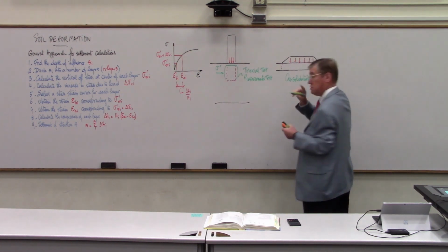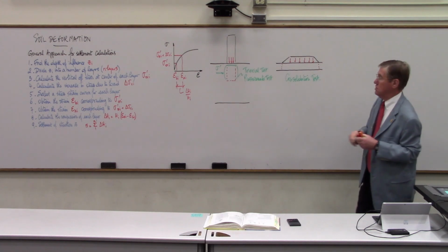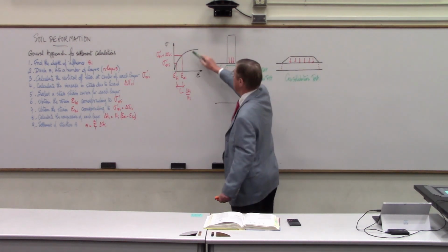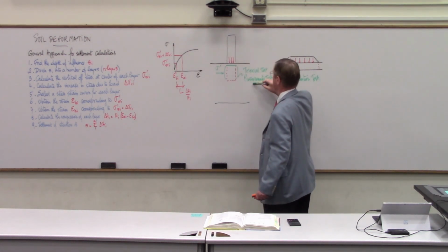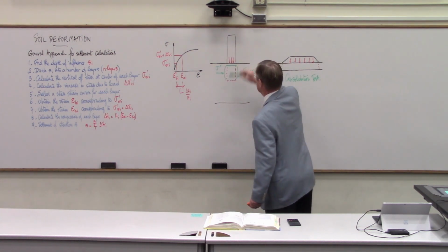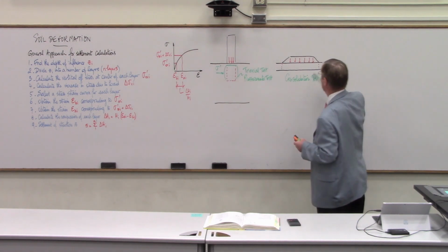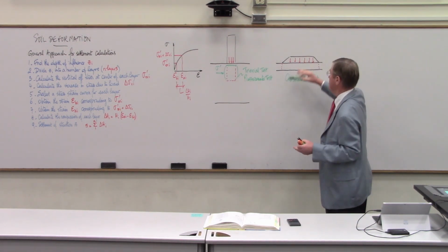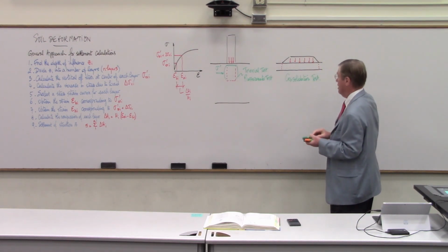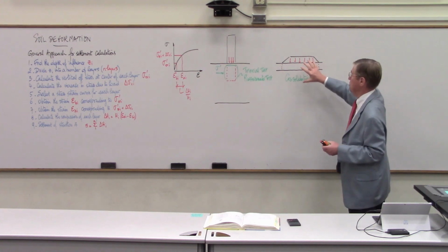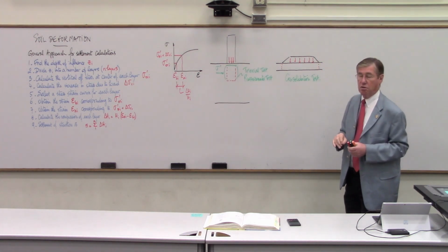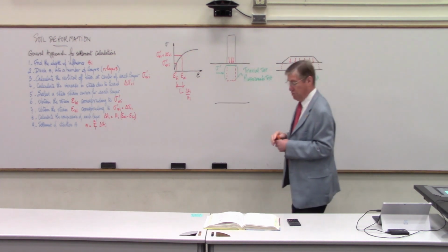To use the stress strain curve from the consolidation test. In other words, that black line here, I would pick the triaxial pressure meter for this type of case, like large high-rises in Houston. But in the case of an embankment or over a fairly thin layer of compressible material, then I would think the stress strain curve from the consolidation test would make more sense.